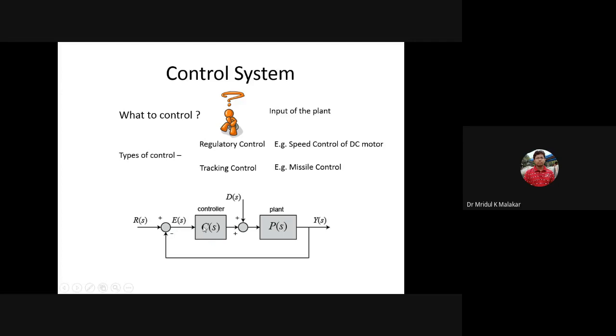So if you implement a mathematical model to understand the system configuration, it is very good. But if you include more parametric uncertainty and nonlinearities, you can see that your controller's parameters also need to change. Maybe you require some adaptive type of control, or a little robust type of control. A PI controller alone is not sufficient for your system. This is just one example.